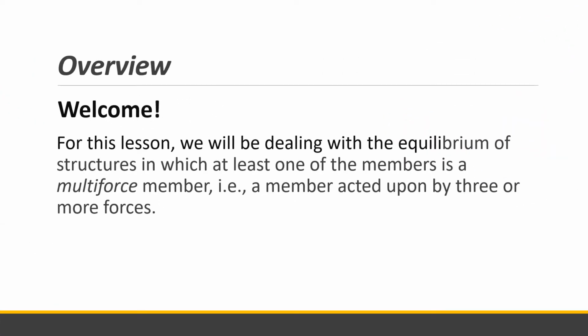So welcome. For this lesson, we'll be dealing with the equilibrium of structures in which at least one of the members is a multi-force member. A multi-force member is a member acted upon by three or more forces. In our truss, the members are only two-force members. But in a frame, it is multi-force.